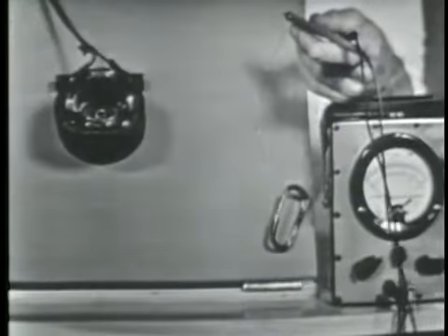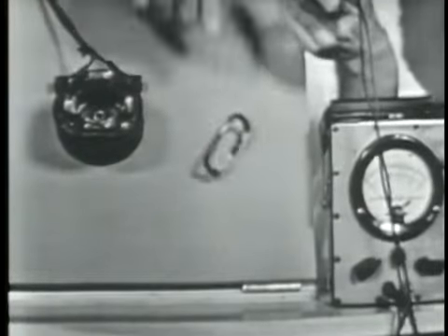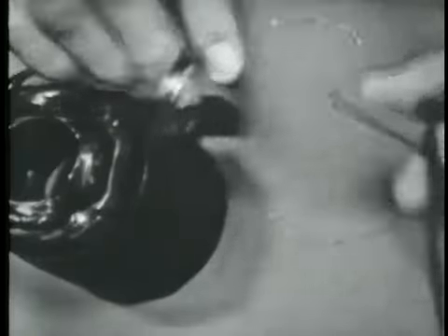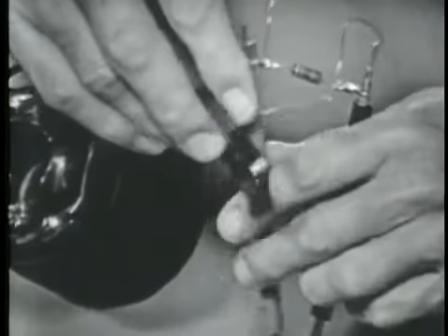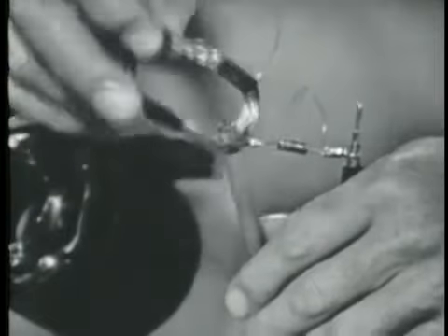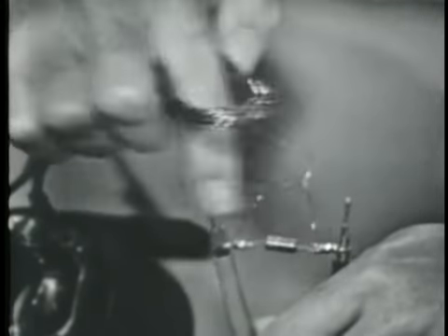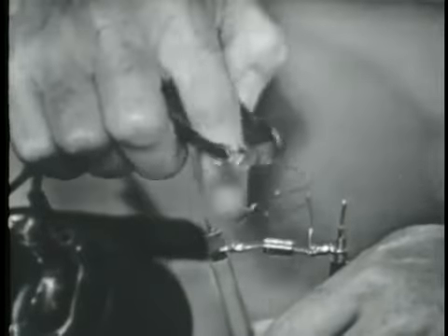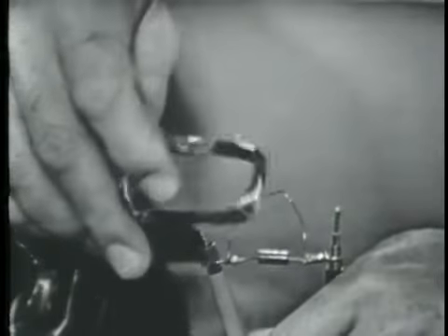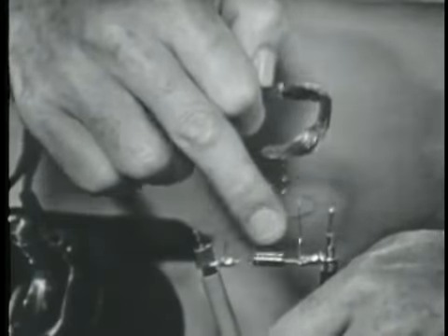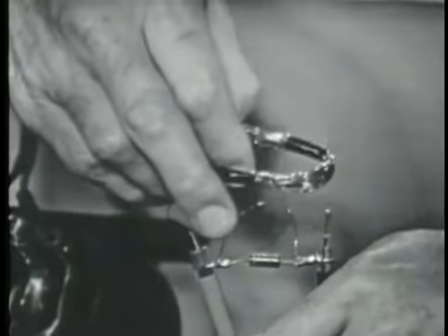I'm going to take the rotor out of there and prove that we have induction taking place. Why don't you explain what you're going to do, Bob? This is a coil of wire. The ends of the wire are connected to a resistor that is connected to the leads on our PSM6. And the object is, if we get current to flow in this loop, we'll have current flowing through this resistor, we'll get a voltage drop, and we'll read the voltage on the PSM6, okay?